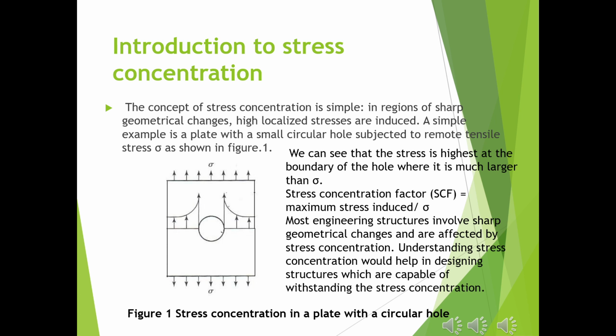Let us say the hole was very small, let us say microscopic. So the supporting area is almost equal to the nominal area. So the induced stress should be equal to the nominal stress, right? But that does not happen. If the hole is very small compared to the dimensions of the plate, we can see that the maximum stress induced is about 3 times sigma, not sigma.